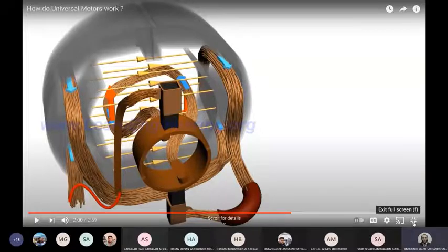It's similar to a DC motor. As you can see here, the flux direction in DC will be constant according to the applied polarity of the commutator. Of course, it will be reversed if the commutator is converted from positive to negative. The supply current and flux will be reversed together, and because they reverse together, this will keep the torque in the same direction.